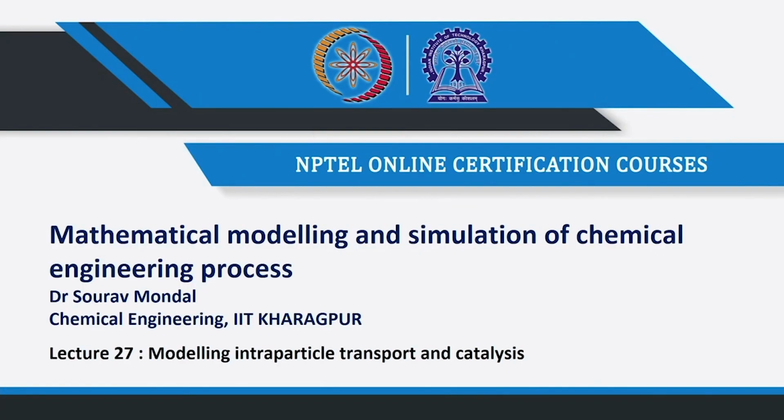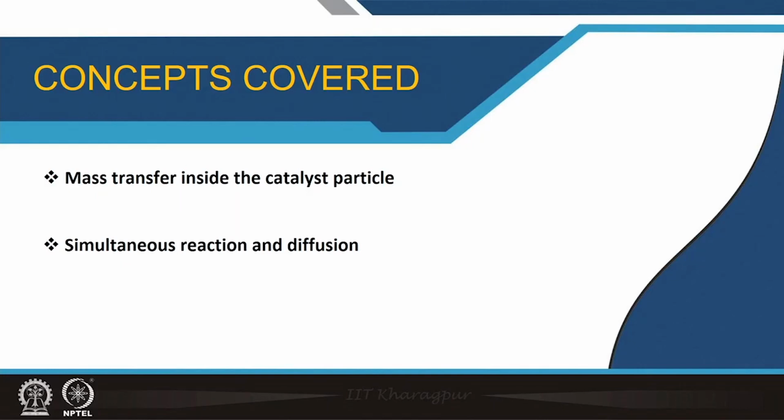Hello everyone, we are going to learn about intraparticle transport, intraparticle mass transport during the reaction. In most packed bed reactor systems, this is something which we often encounter. Especially in the case of packed bed catalytic reactor systems, we often see that the mass transport inside the catalyst particle plays a big role in determining the overall conversion as well as the performance of the packed bed reactor.